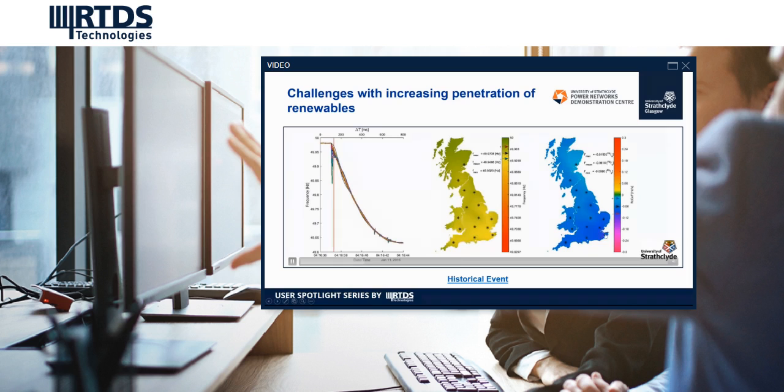So we can see a clear characteristic at the event location. By analyzing the frequency and RoCoF along with the angle measurement data, we will be able to locate where the event is in the system, and therefore we will be able to dispatch fast frequency response closest to the location of the event.